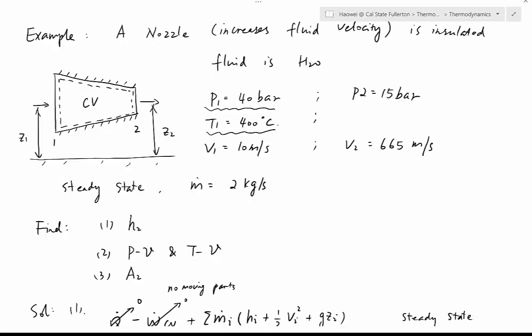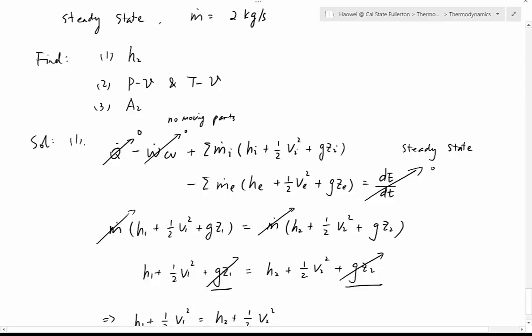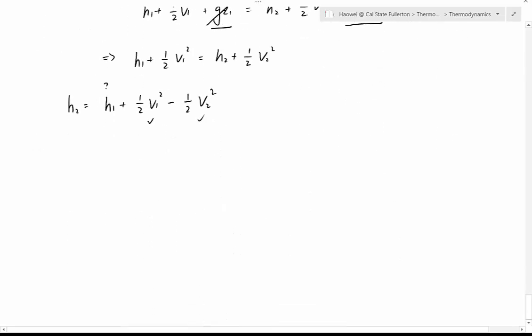And if my actual temperature is even higher than the boiling temperature, which we call saturated temperature in this class, what does that mean? That means your substance must be at superheated state. So if your actual temperature is higher than the saturated temperature, then your substance must be at superheated state. Okay, so now let's see if this is true for this problem.